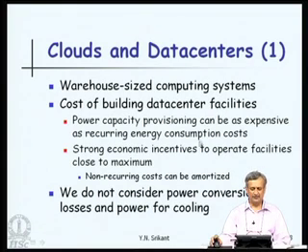In fact, apart from the computing elements, we need to worry a lot about the power capacity provisioning as well. How much power capacity should we provide for a data center? Power capacity provisioning can be as expensive as recurring energy consumption costs. So, we need to build generators, UPS stations and so on, and this becomes very important. What happens is you could be providing a large capacity, but we may not be using all the capacity. So, you have wasted a lot of money in building the power plant and so on, with a capacity which is more than what is needed. But if you provide very little expansion possibility, then you may get saturated very soon, and you will not be able to add more servers and more equipment to your data center.